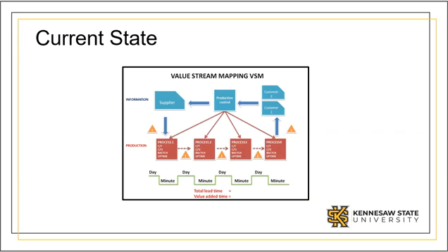As you develop your understanding, make note of the time it takes to transform the raw material into the product. This is the value-added time. Also make note of the time it takes one piece of product to move through all the processes. This is the lead time.